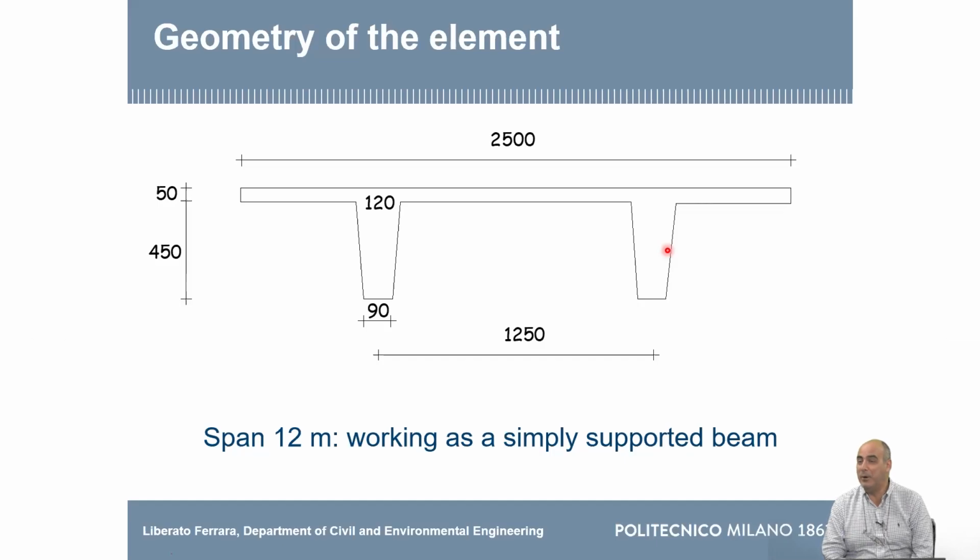Yeah, it's just for demolding. You remember the day before yesterday, we said that there are some passive measures to ease the demolding. This is one of them. Design a shape, as if you have a rectangle, you have just to extract the rectangle from the mold. And until you do not fully take it out, you will always have some friction. Here, you just need to lift it up a little bit and it will be completely detached. So it will be much more effective from the demolding point of view.